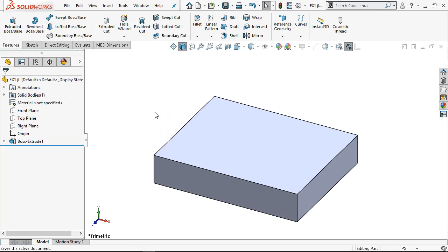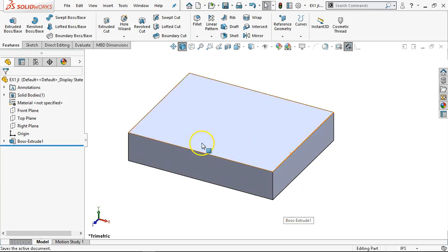So we have a couple of methods to start looking at the tolerance zone. 0.5 by 2.5 by 2 is our sizing, and we want to be able to visualize what those tolerance zones can look like. So for the first one, let's say that we're going to have flatness across the top. First one, I'll generate a plane, and these are going to be very similar in the creation, but not so much in